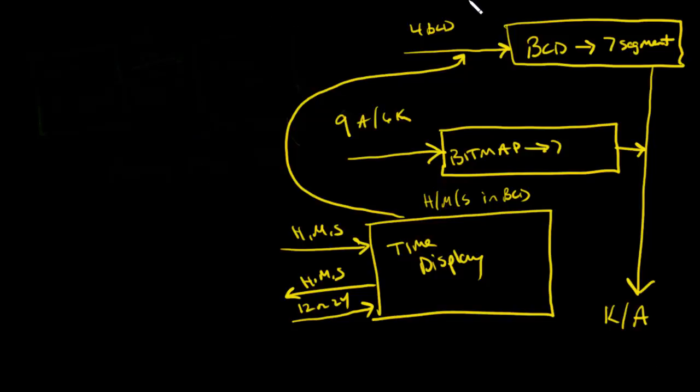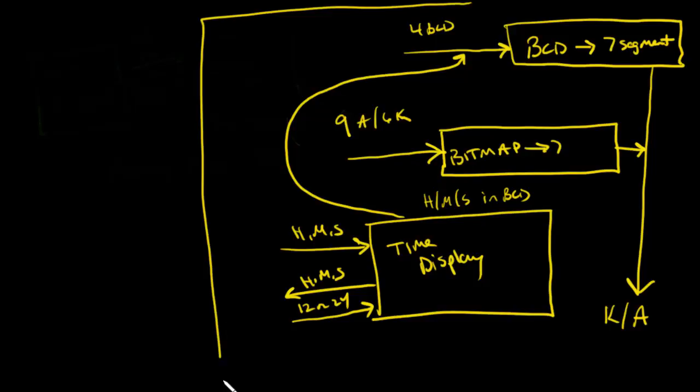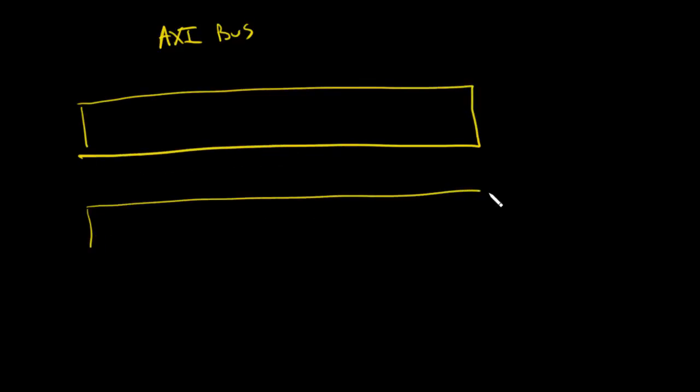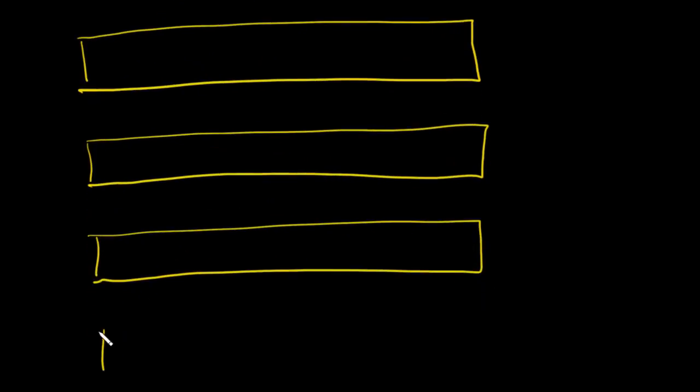And to make this all happen, all of this needs to somehow get its control signals from C language, from the memory map, from memory loads and stores. And that becomes the grand challenge. How do we make that happen? Well, what I'm going to do is I'm going to have my peripheral that sits on the Z board's AXI bus, and that's going to give me some number of registers. We're going to pick 4 registers.